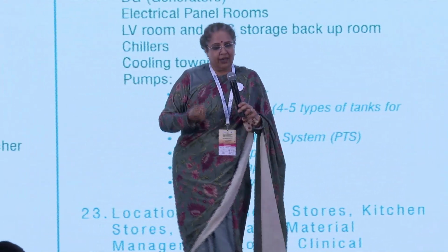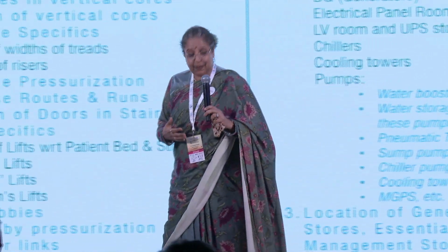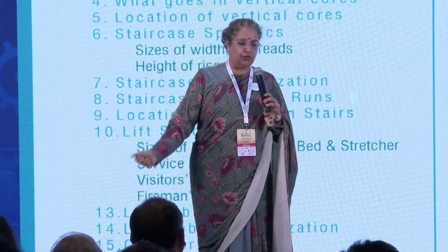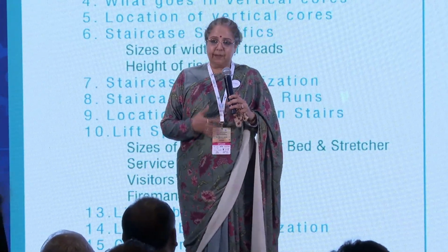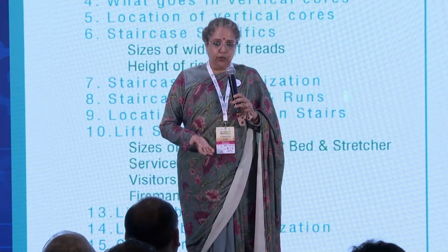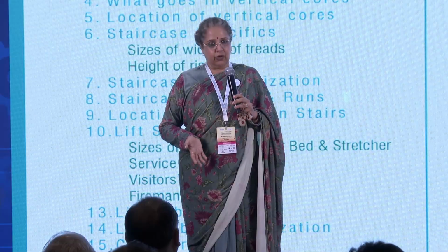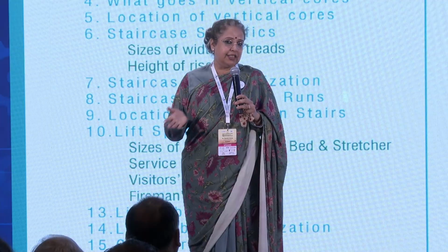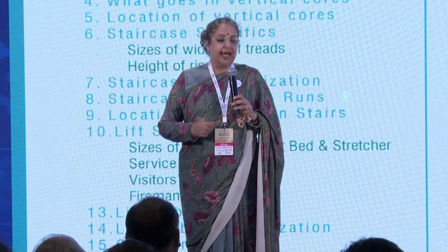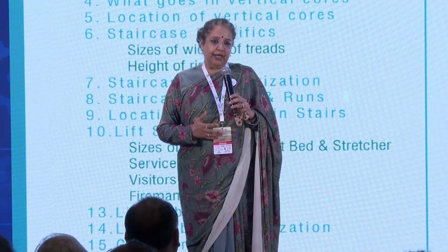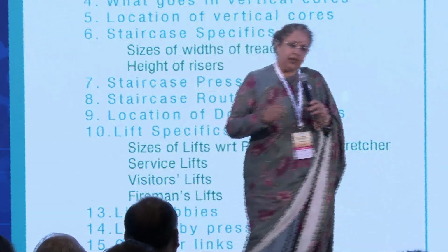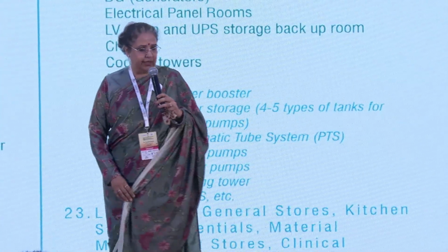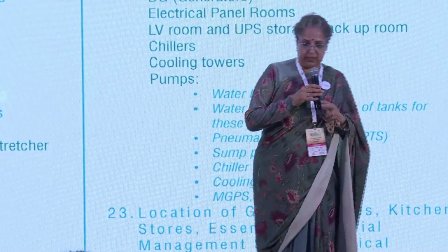We usually put these things in places where one thinks, okay, we need to place an AHU room close to a department, but if we are able to stack these MEP rooms in vertical core or in all the vertical cores, and very selectively through experience of the architect, that is where we are doing wholesome work, and at the same time we are able to bring in quality and cutting down time, and this comes through experience.